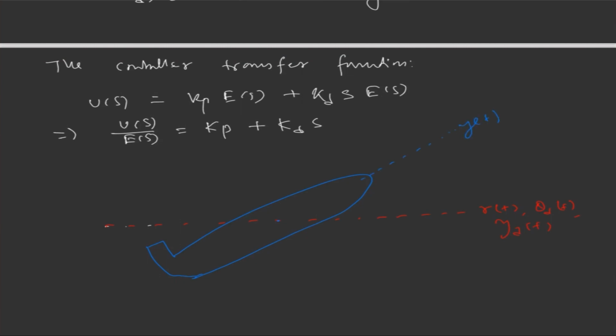In proportional control, we have a spring here, and in derivative control, we are adding a damping term in this expression. So due to the damping, the oscillation, which is due to the spring, can die out. So this is the error. The error may initially have some oscillation, but after some time, due to this damping term, it will go out.